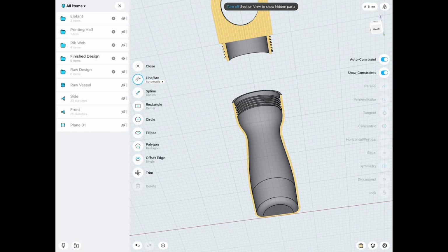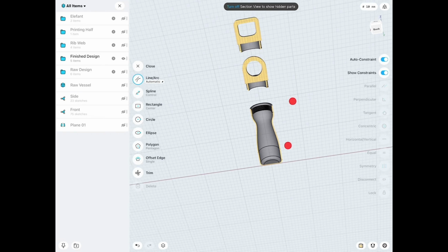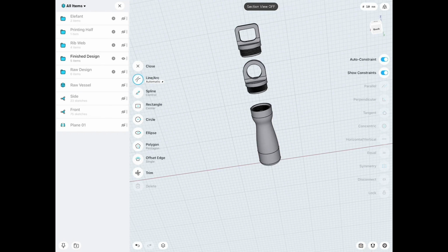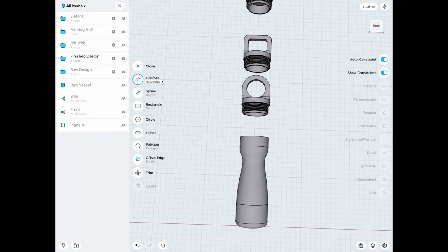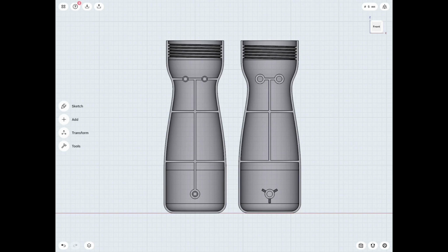So then this way, if I want to send something later out to like a fine print in SLS, then I can adjust everything to the values I really only need. And that's a great direct modeling capability Shaper 3D offers us. Let's continue talking more about the wall thickness, because there are a few more elements which are really useful to be aware of. This also then goes into print stability.